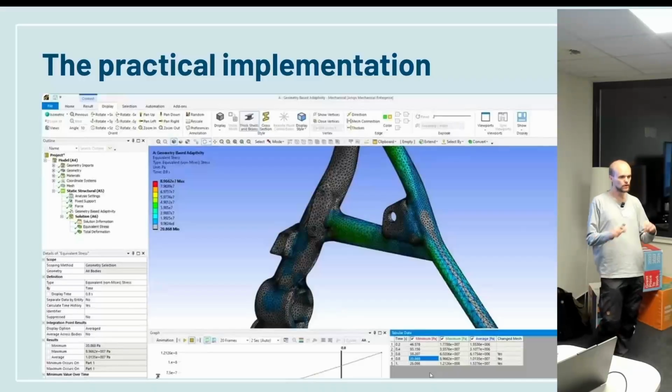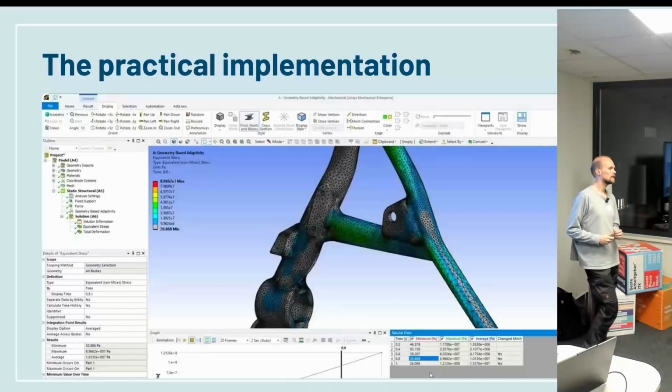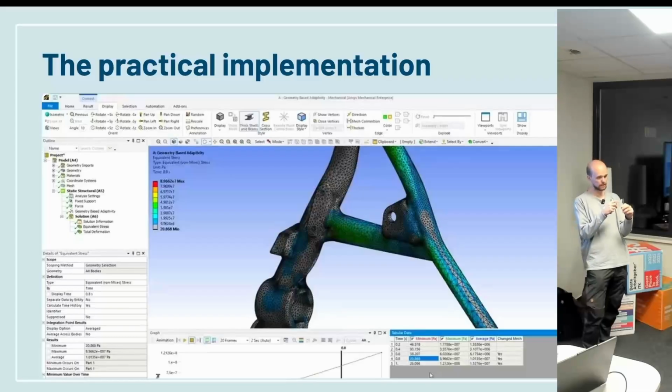So you have very complex geometry, and you have conflicting goals. First, you want your mesh to approximate that geometry as closely as possible. And second, you want your elements to be as close as possible to their original shape. For example, a tetrahedron with equal edge length. And these conflicting goals have to be brought in line with each other.